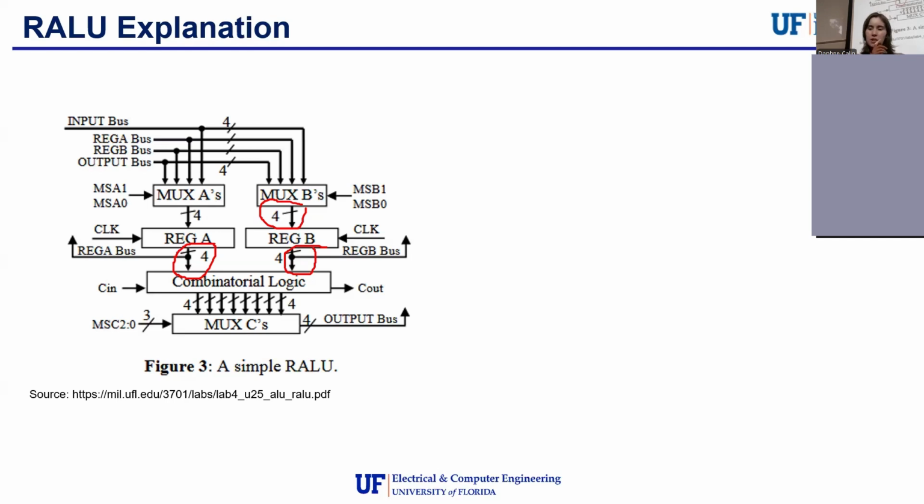It doesn't really matter as long as you're not trying to use it, but it will change based on the values of A and B, whether or not you're selecting the sum function. Yeah, it might be easier to see once you build it in Quartus that you just connect the cout output from the 4-bit adder to the output. So the 4-bit adder is always adding, no matter if add is selected. Yeah. And so that's why when I went through the table, I was always checking the cout, because it'll always happen without you even selecting it, and it'll even happen without a clock.